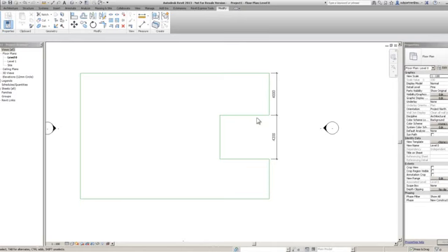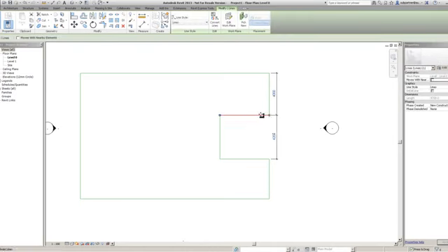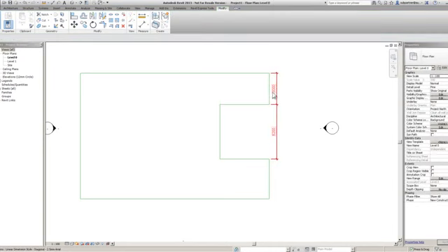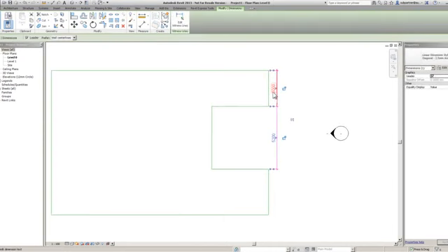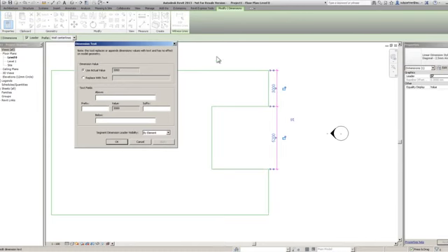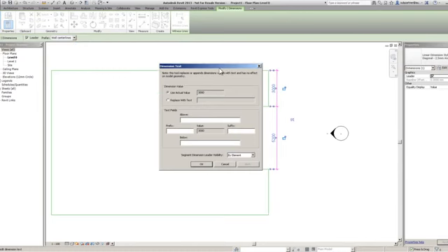Just watch what happens when I select it. Select that line, and you can see how the dimension's actual text input has gone blue. It means you can pick the dimension, say 3 meters, done. Doing it the other way round, highlighting the dimension and then picking the box there, is basically our dimension text editor.